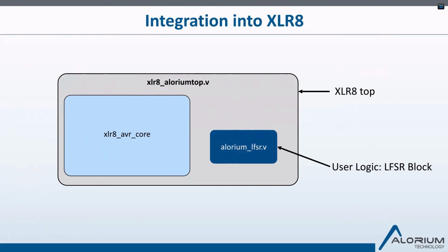That's the example we're using, a linear feedback shift register, a fairly simple design. It's very handy for doing things like random number generation. We're going to look at what the code looks like to implement this. First, we'll take a look at what it would look like to do in software, and then Brian will show us what that looks like implemented in Verilog.